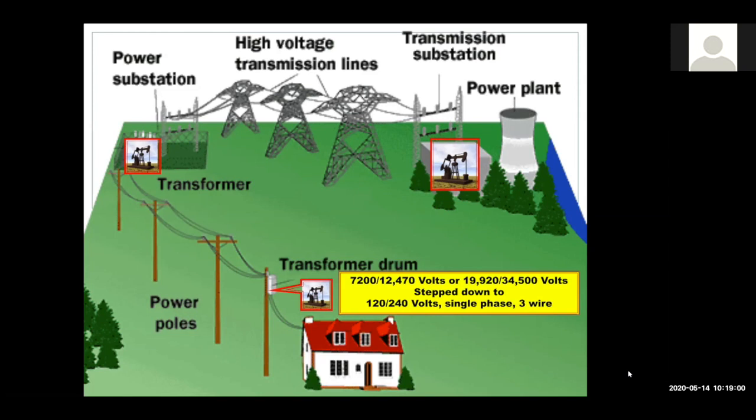But the wire that comes into that home or business, but we're going to talk home, the wire that comes in, that's 120/240, comes from a transformer. That pump jack I have out there on the pole is the transformer. And let's be sure about this. Whatever comes out of that transformer, meaning the line voltage that comes out, goes to the house, goes through all your appliances and everything in the house, and comes back to that transformer.